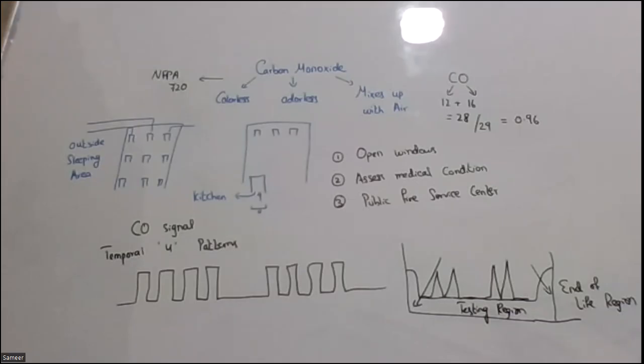We also request a bathtub curve from the manufacturer, and they can provide one based on their previous projects and previous installations. This is the last project. We made this one for a specific company, the facilities management, who requested it. We made it based on our visits and the year of installation, like 10 years, and the number of visits we made is approximately 2. So they identify that the failure rate is very low. Like this, they can also represent it, and we can also make our own.